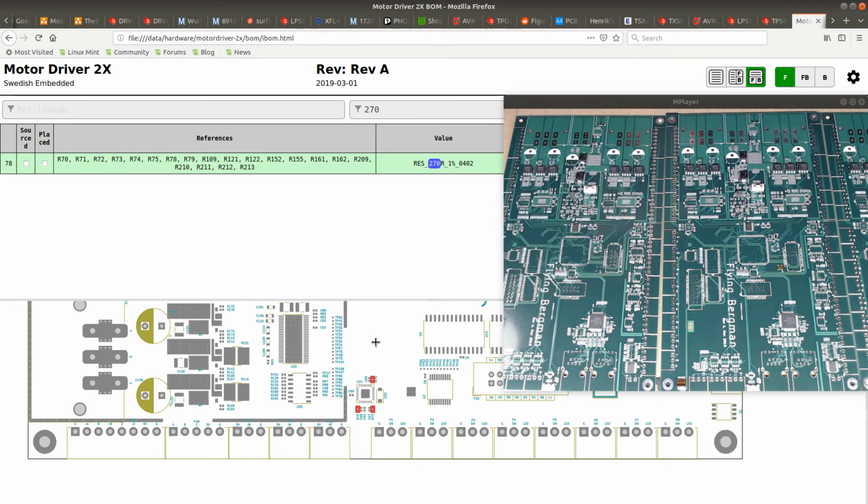Now, does plus mean pin number 1? Yeah, I think so. Okay, this is a QFN package, small QFN package, but that's no problem. I just place it on the solder paste.